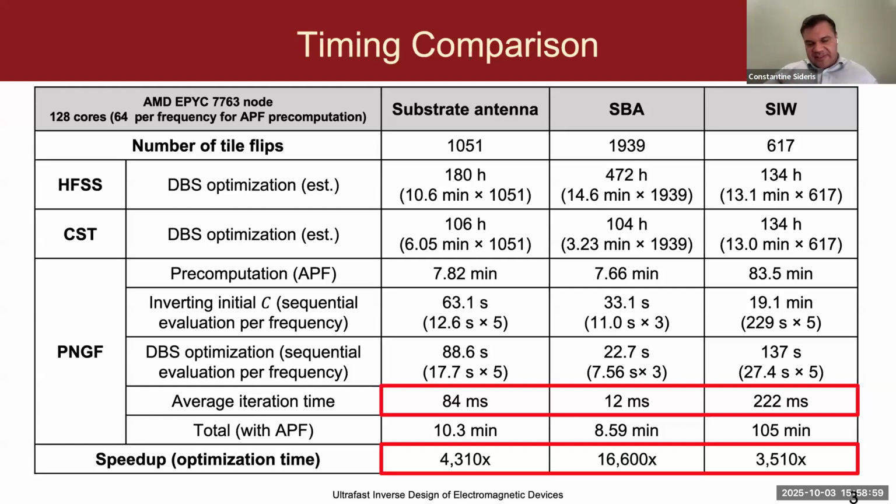In the corresponding HFSS simulations where we compared it, we actually used the true metal thickness of the PCB that we're going to fabricate, just to make sure that the design we fabricated should actually hopefully match, and those did match pretty well. However, in the most recent work that we're doing, where we're using true mesh-based methods, method of moments integral equation-based solvers for precomputations, we are fully representing the 3D metallic structure and the thickness and the loss and everything of that. So that is being accurately represented in the 3D electromagnetic solver.